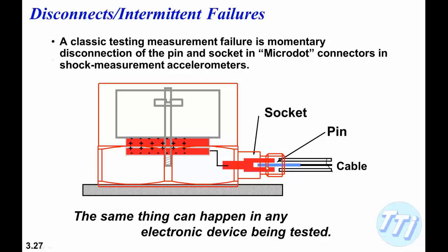The female part of the connector had been expanded by the oversized pin on the cable, so when we put the correct cable in, we got intermittent disconnects. Needless to say, this is going to fail right at the maximum acceleration or near the maximum acceleration that you're seeing. So obviously this would have corrupted the test that we were doing.